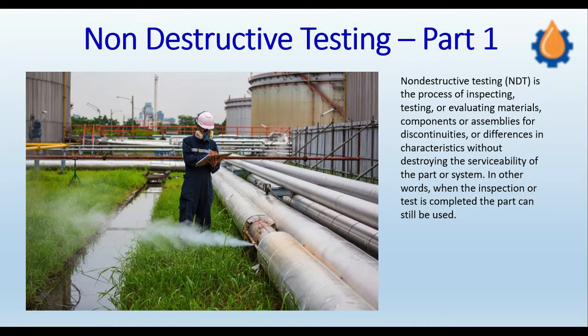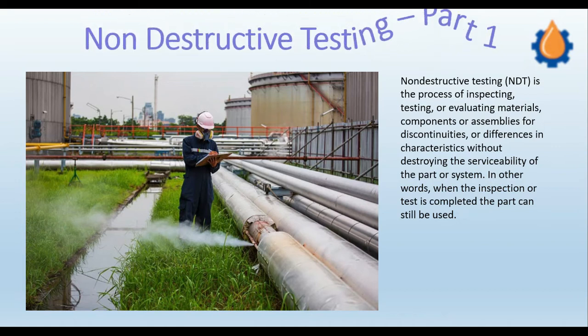There may be a doubt in your mind that if the welding itself is destroyed, then what is the purpose of welding that earlier? So actually the component itself is not destroyed. A certain part of that component is intentionally left, which is called a coupon plate.